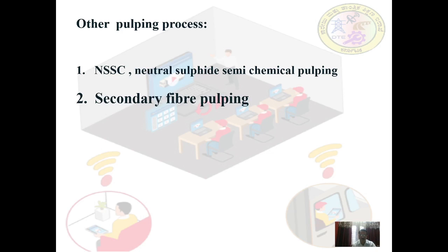The collected material is repulped in water, cleaned of objectionable dirt and contaminants. Then it is subjected to a de-inking process with alkalis such as sodium hydroxide, sodium carbonate, sodium oxide, and then washed with mild alkali.